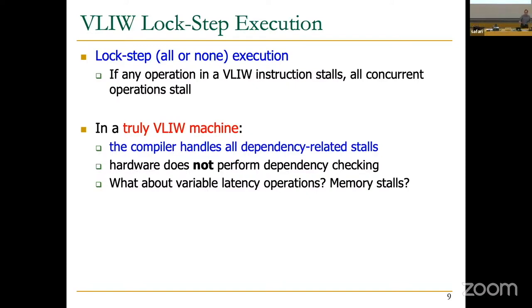In an out-of-order machine, what happens? A load takes 500 cycles, fine. Keep fetching instructions, buffering them. In the reservation station, some of them will execute, some of them may not execute. So the model handles it without any problem. The hardware cost may increase, of course, if you really want to not stall after 500 cycles or 1,000 cycles or 2,000 cycles. But the model itself doesn't have a fundamental issue as to what should I do. You know what to do. You basically stall the load and the dependent instructions, independent stuff can execute.